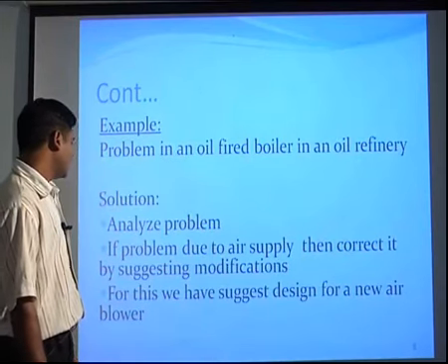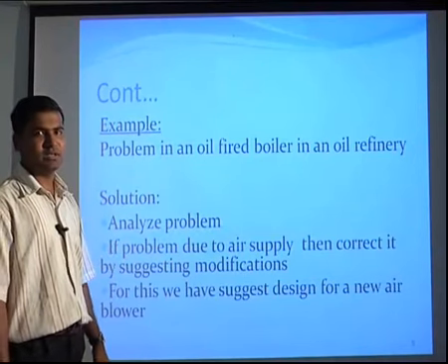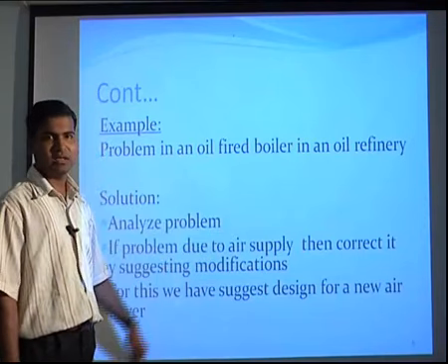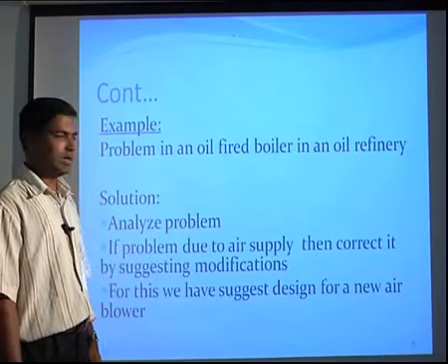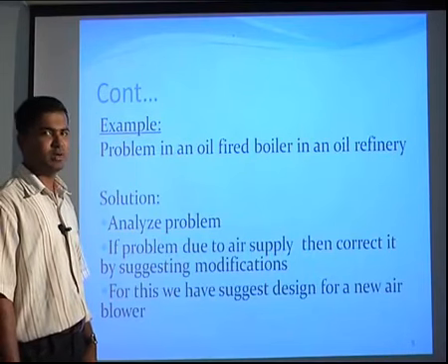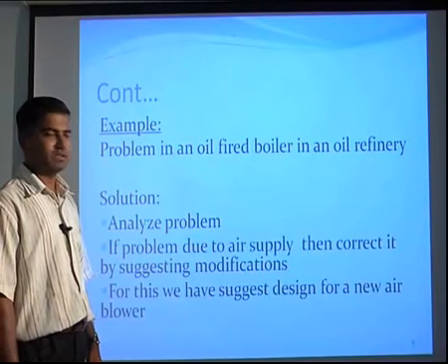Suppose the problem is that the combustion is not complete. That means there may be some problem in the air supply. When fuel is burning, if the air supply is inadequate, then the burning will not be complete, and the efficiency of the oil-fired boiler will go down.